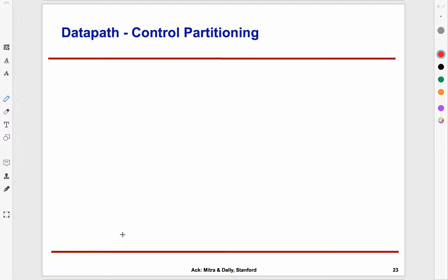So what that leads to is a more general view of what sequential systems are. It is true that all sequential systems, the ones which we can implement, are finite state machines. And if we so wished, we could always write them in terms of a state chart with arrows going all over. But if we have quantities with a large number of bits, like a 32-bit or 64-bit register, and potentially many of them, then writing them explicitly in terms of states is basically out of the question. We have too many states.